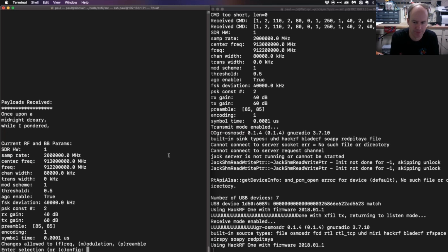Cool. Now, Paul had a question. He said, building a frequency hopping scanner has the same problems as detecting Wi-Fi in different channels, except scaled up. SDRs have a limited range they can look at depending on the device, and limited bandwidth, as well as different frequencies. So how would you go about dealing with something that is frequency hopping when you're reverse engineering, to be able to pull it out of the air and look at it? There's a couple different challenges on frequency hopping.